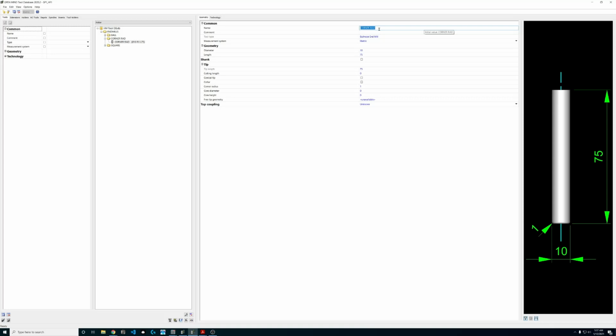We use a pretty unique naming function here, and it's designed around really quickly being able to identify what sort of tool this is, even when it's buried in a magazine or something. But let's keep it simple for this video, and we're just going to call this SGS. We'll start with a D12 end mill. R, we're going to use 1.5. Now, EDP. I stick it right inside the name. So for that tool, it's going to be 44814. I stick it right there at the end.